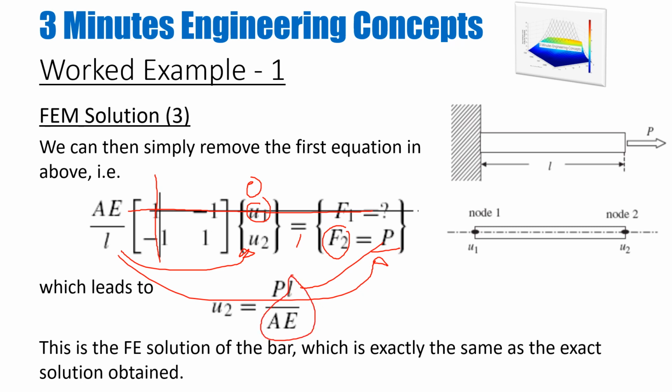So this way I can find out my displacement at node 2. And you remember this was the same value we got from the exact solution or analytical solution. If we don't put this L here and we say that we want to find throughout the element, then again we can vary L and we can find out at each point in the finite element what is the value of U2. Once we know the displacements, we can compute the other quantities.